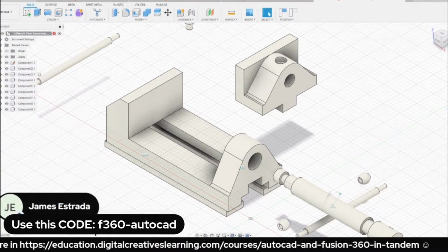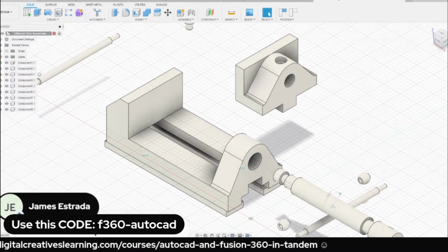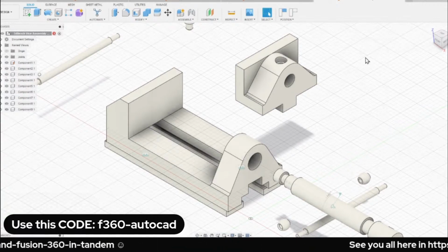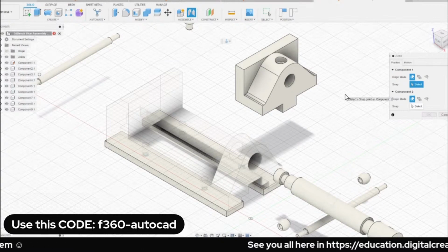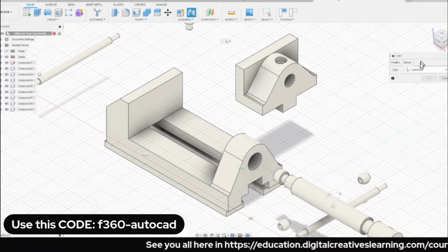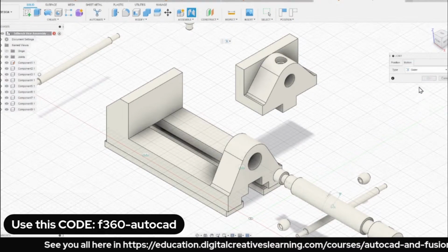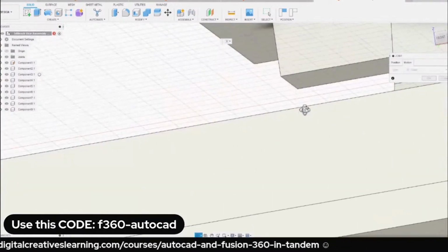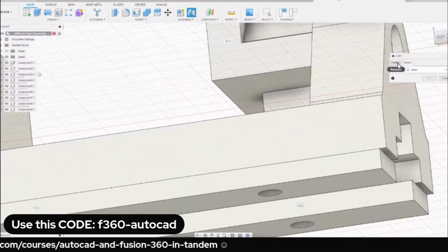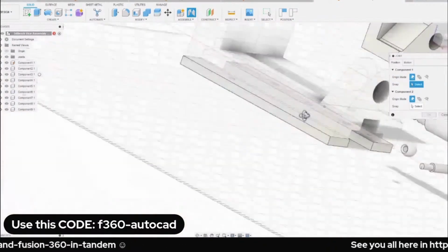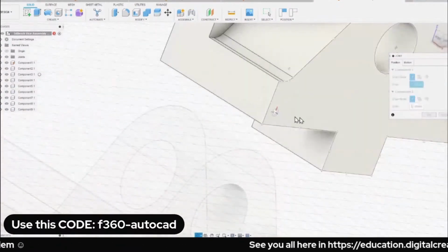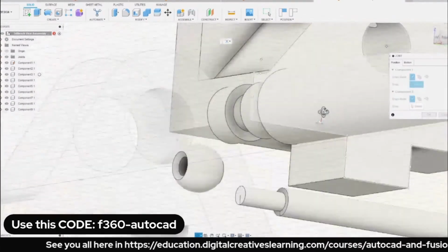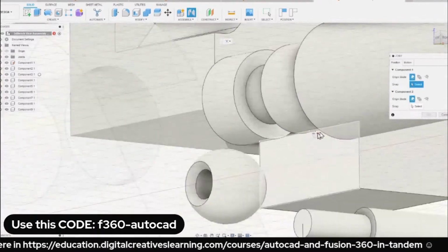Yes, Sir James is correct. Linear with respect to the shaft. So for that linear, it's actually called slider in Fusion 360. So with slider, I will go over on this edge. But of course, heading over to position tab. Again, take note of the joint origin or this disk's position. So I'm going to head over to that edge.